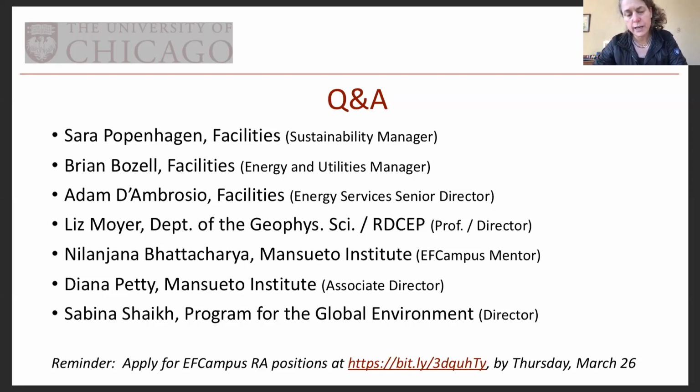Yeah. So site EUI will undervalue the electricity, and therefore it won't be tied to the cost, right? So source EUI is an attempt to say, what is the primary power required to service this building? And that includes all of the energy, the fossil fuel that went into making the electricity in the first place. So the simple hack is just to take your building electricity use and multiply by a factor of 3. Cornell typically reports, if you look at their website, site EUI and not source EUI, so you have to correct for that. I've done an attempt to correct for that from Cornell, but you can find that on their website.